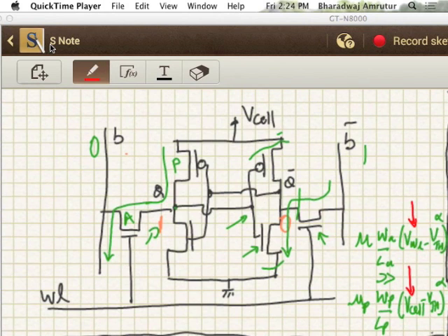Whenever your voltage source needs to supply a lot of current, the design of that voltage source becomes difficult to do using only on-chip components, because you need to go towards more of what you would learn in power electronics. Probably you need to go for buck converters and those kinds of things. But on chip, when the load requirements of the power supply are small, you can use on-chip circuits. There are various circuits which will allow you to generate these on-chip voltages.